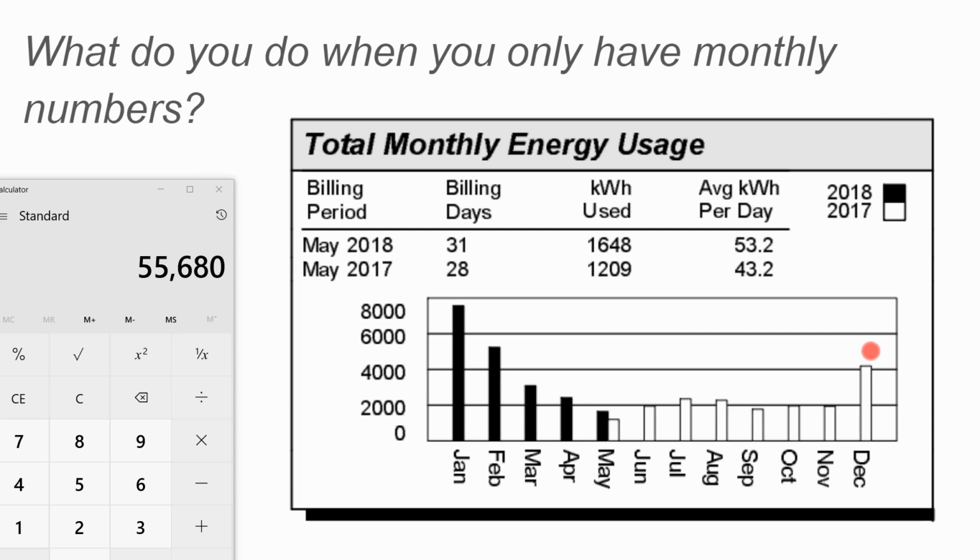If you had their 15-minute interval data, such as most businesses have because they're billed for their maximum 15-minute demand, they might get a report that has every 15-minute increment of their building's energy use spelled out for the entire year. That data is very useful for right-sizing the system.